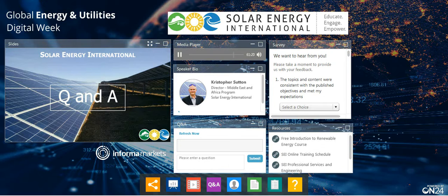If the utility has no regulations, then it means they also don't have a contract or an agreement for exporting power into their utility system. So the first question I would ask is, am I allowed to export power or not? If they don't have any plans at all so far, it means they also don't have a contract set up or an agreement on how to measure and value the exported power to the grid.